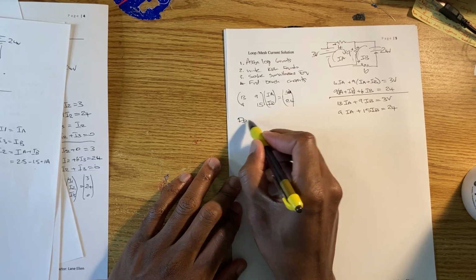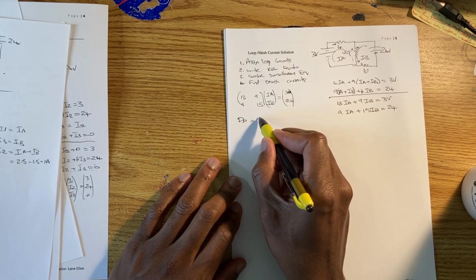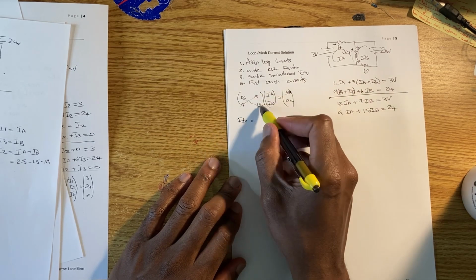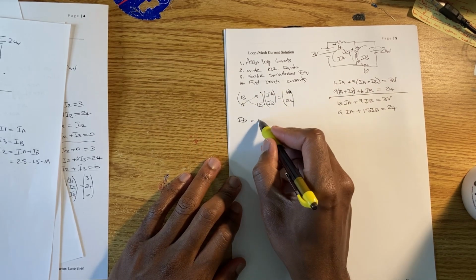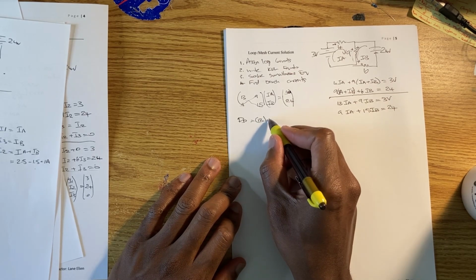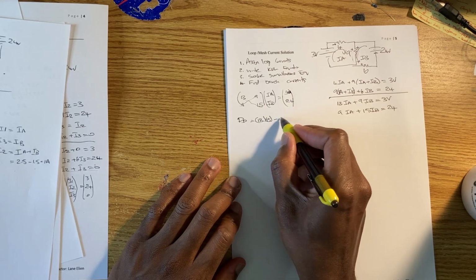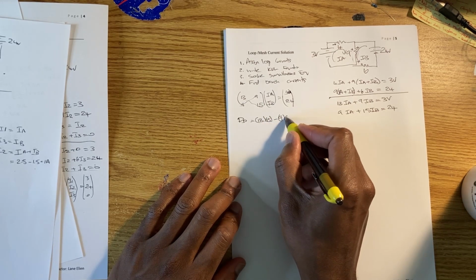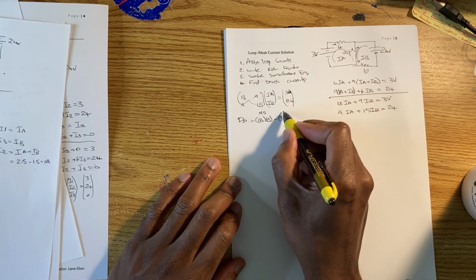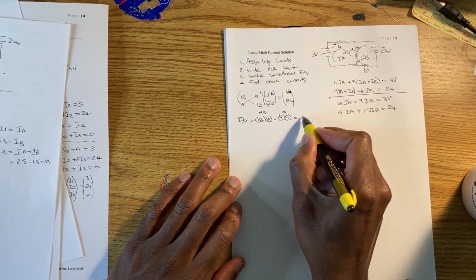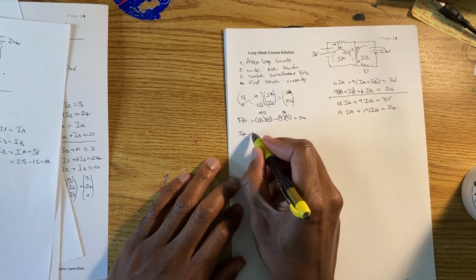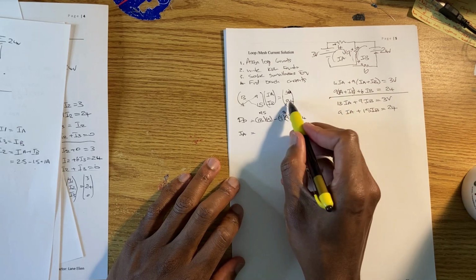Same thing, we'll do the determinant method. So the primary determinant is going to be equal to, we multiply these 2 and subtract from this one. We're going to have 14 by 15 minus 9 times 9, which is 210 here and 81 here, and our answer is 114. Then to find IA, we put the answers in the first column.